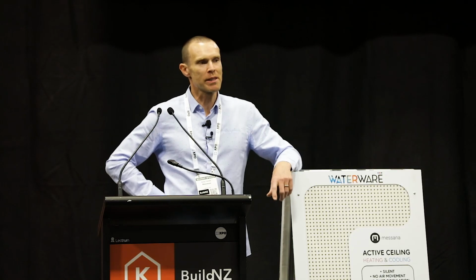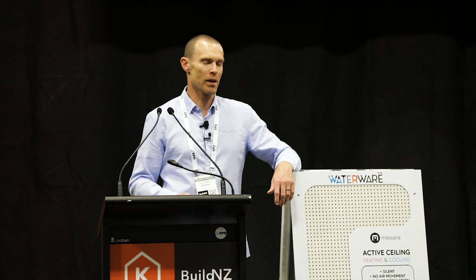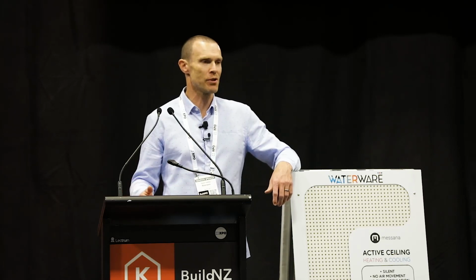It depends on the size, I suppose. Yeah, it depends on whether you've got excess capacity in your appliance or not. Generally speaking, the appliances come in a range of sizes. For instance, for a single phase appliance, we do a 10 kilowatt and a 16 kilowatt. So if you're in between sizes, if you needed a 12 kilowatt for your heating duty and you've got a 16 kilowatt appliance, then that gives you 4 kilowatts worth of extra capacity, which you could use, yes.